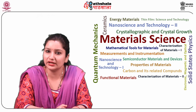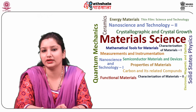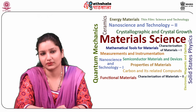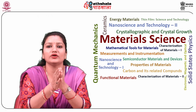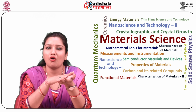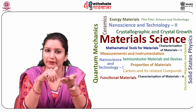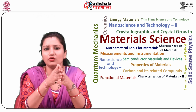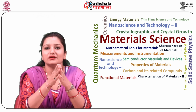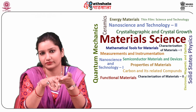When the surface is cleaned, the photoresist is applied using the spin coating technique. A viscous liquid solution of photoresist is dispensed onto the substrate and the substrate is spun rapidly while being coated with the photoresist such that it bonds uniformly to the surface.